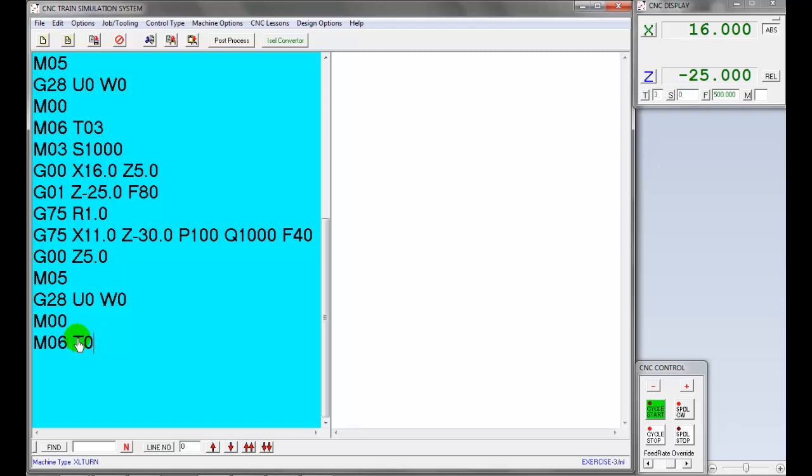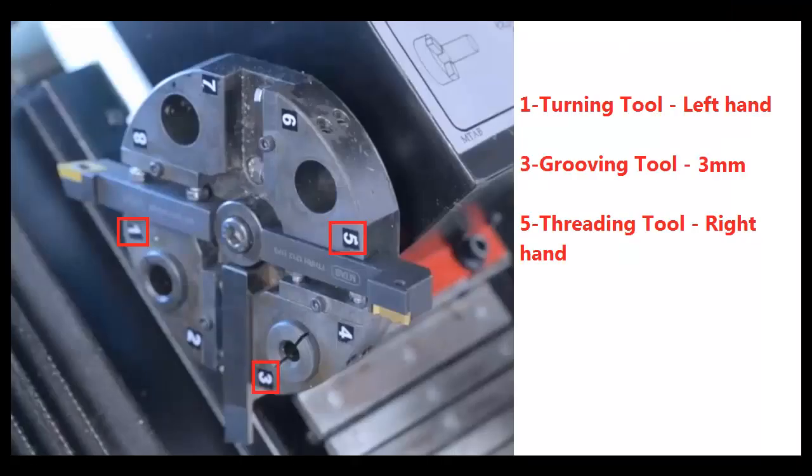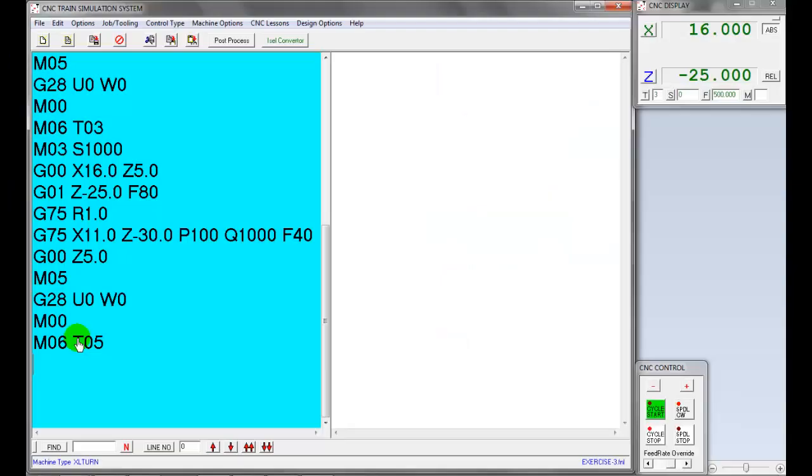M06 is tool change command. 05 is threading tool is mounted on turret 5th position. M03 is spindle on clockwise direction. S is spindle speed 1500 revolutions per minute. Note, we are going to machine right-hand threading in the given workpiece.